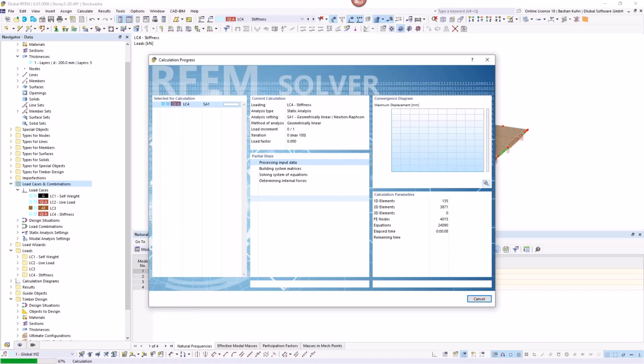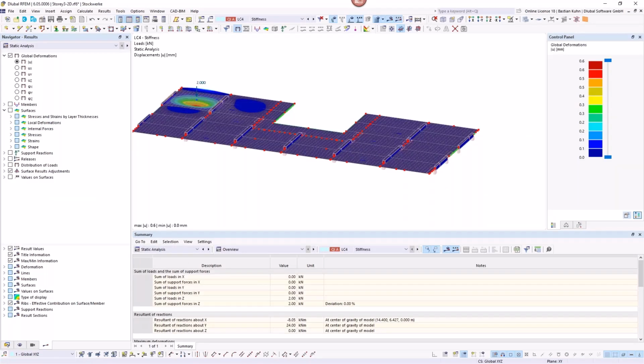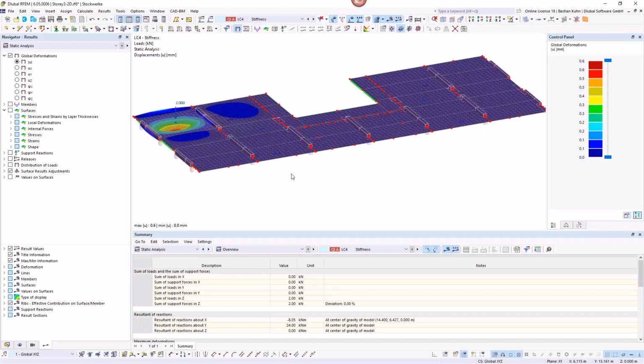Well, it requires that you have an option to calculate the frequency rate, and this method can be even more sophisticated than what I'm showing in here. It would also be possible to analyze this with our software, but there you have to define a vibration on the structure and see how the damping in the structure works. But as with these rules, we are below the level of 1 millimeter, you can argue that the vibration is fulfilled and that it is okay.